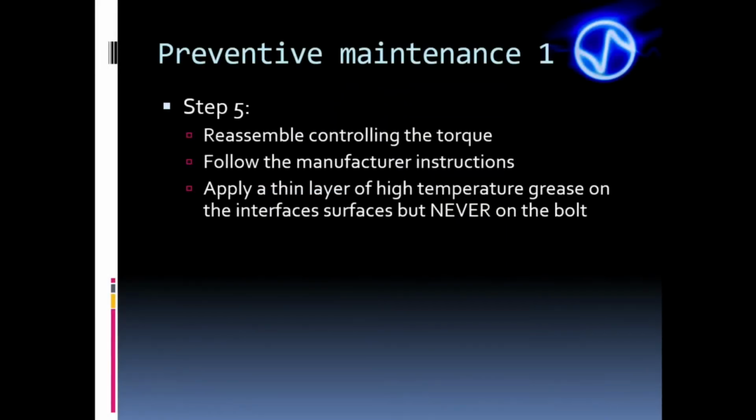Other typical damages caused by tension concentration are the cracks in the elements around the stud region and the stud breakage itself. After reassembly, the frequency deviation should have been reduced. If it has not reduced, maybe there is a defective element. In this case, we should perform a preventive maintenance too, which we'll learn ahead. But we are not done here yet.